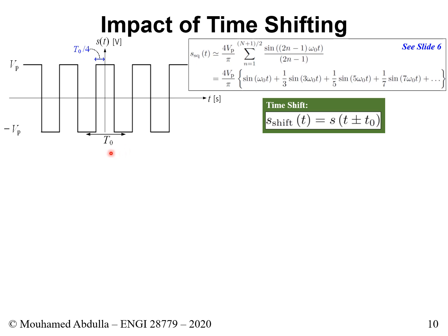Now, what would you do to find a DC component? Well, you could just look at the average. The average is 0, so we know that although it's now an even signal, it still does not have a DC component. Or you could measure this area, this area, this area, and this area. You'll realize that this is a positive area, this is a positive area, this is a negative area, this is a negative area. You add them together, it is 0, and therefore the average around the period is 0, and therefore you have no DC component. So that's just related to the previous slide, but I still wanted to mention it here.